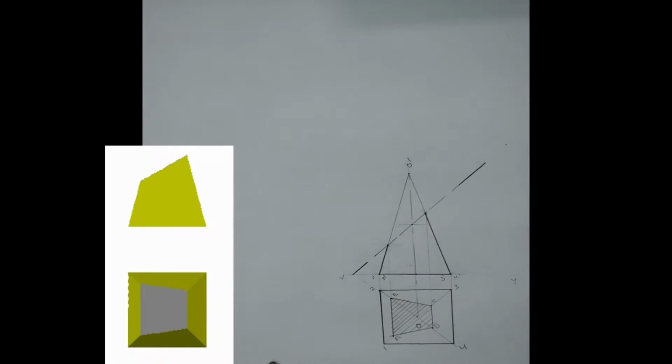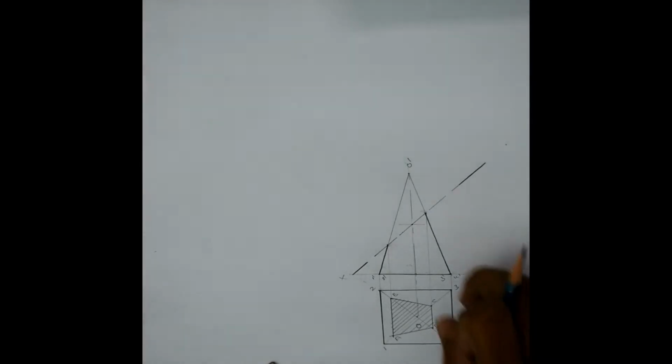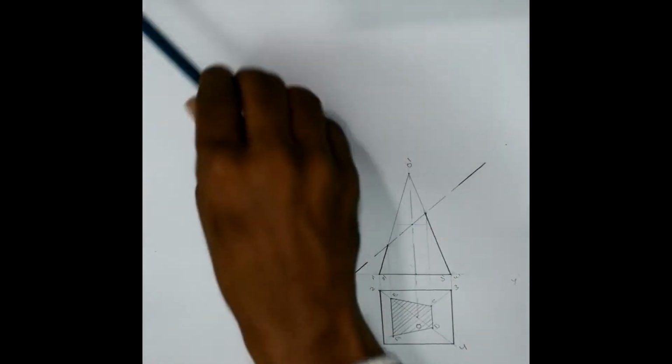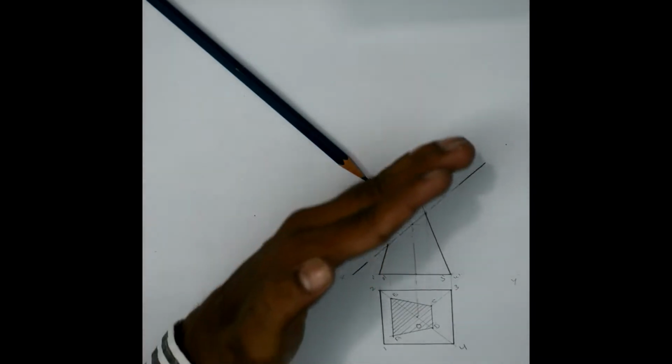But here in this question it is also mentioned that we have to draw the auxiliary view, or also known as the true shape of the section. If this portion has been removed, as I have explained in the earlier video, that the auxiliary view is a view from other than the front view, top view and side views. So this is our front view and top view. The auxiliary view will be in this direction. In this direction.